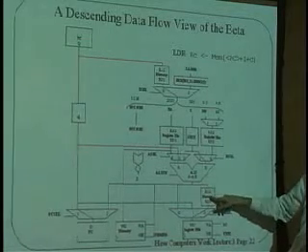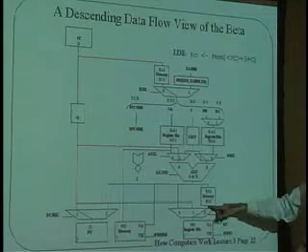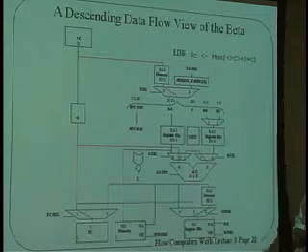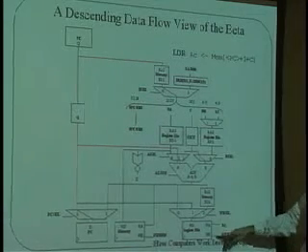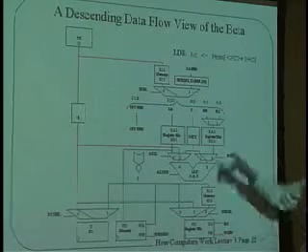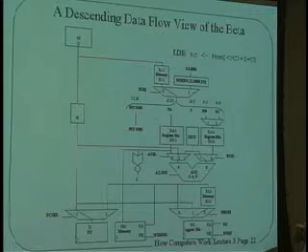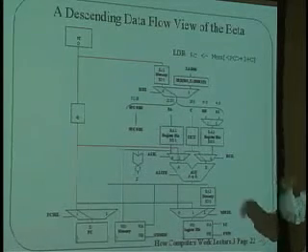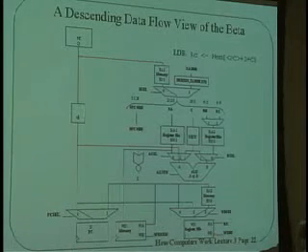We feed that into a read port on the big slow memory. The data that comes out of that is chosen here. Then we put that in the write port of the register file, feed RC into here, turn this on, and go bang, and it does this opcode, LDR. So it's just a way of saying, find a word close to the PC at a certain distance from the PC and load it into the register file.